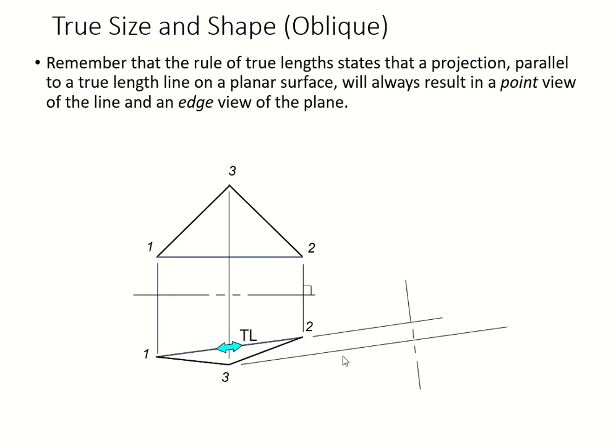Now we're going to start with our projectors. Then we're going to put a fold line perpendicular to these projectors. These are projector lines. Since this is your true length line, we're going to draw extended out of it, parallel to that perpendicular fold line. What are we doing? We're going to draw the last view, which is your right side view for this problem.